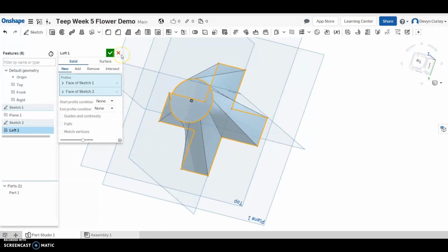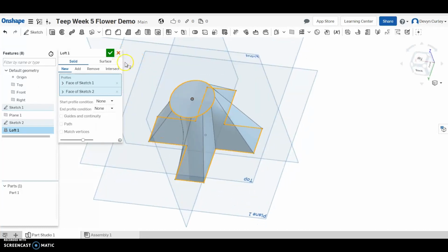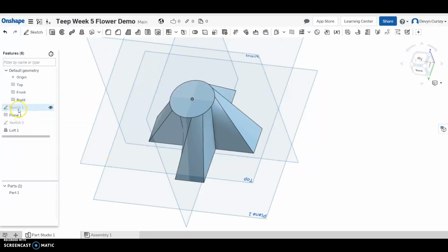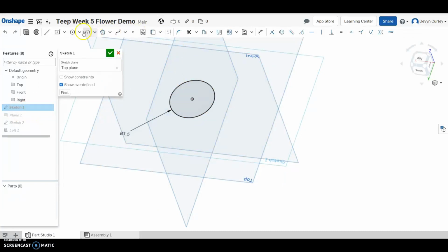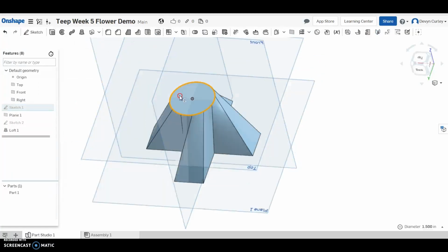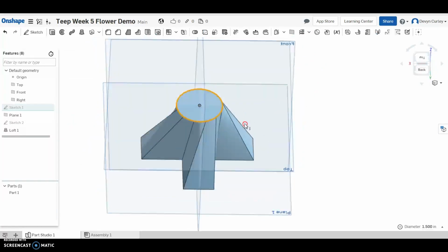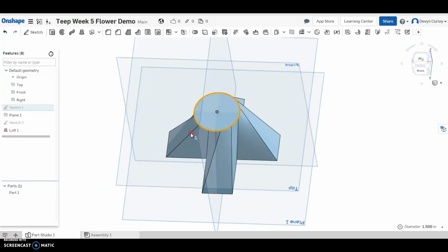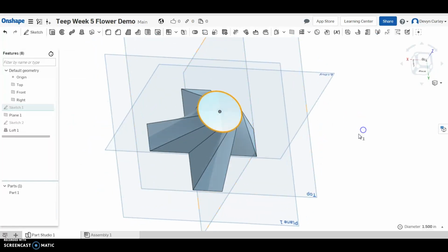If I wanted to be extra careful with it, if I were to go back into Sketch 1, you can create your circle with a series of arcs, which will then add vertices to it where you want them. So essentially, you could break it down into the quadrants you want those lofted steps to come up to. But for right now, I'm going to say this just looks really cool.